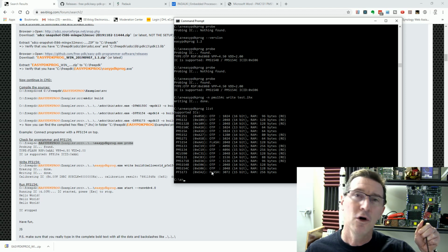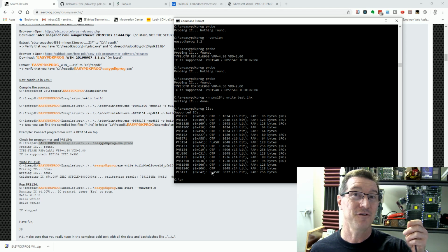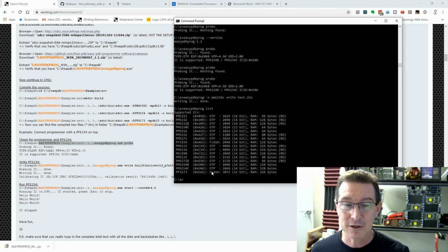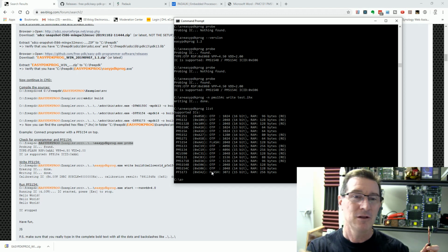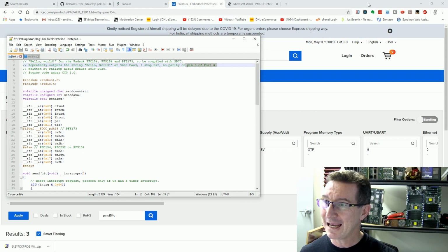And as you saw before, we used 900 and something bytes. So we're using like half the memory just to do a hello world. These things are not designed for huge programs, but printf takes a lot of space. If you hard coded that in handwritten C or something like that, it'd be much better. All right, so this writes hello world on pin 0 of port A.